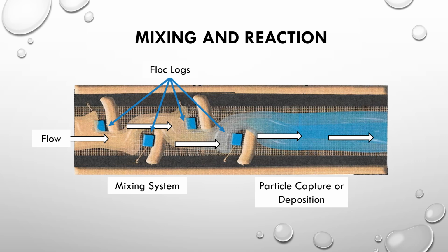And then we have that snowball effect where it hits more and more sediment, binds more and more sediment, and eventually it makes this large flock that can be settled out or captured. So again, that mixing and reaction is very important. If we are treating and discharging into a sediment basin, and I put that flock log right at the discharge into a sediment basin, you can essentially look at that sediment basin as being a stagnant body of water. If I put a flock log into a basin, it's not going to dissolve, it's not going to mix, and it's not going to have any effect.